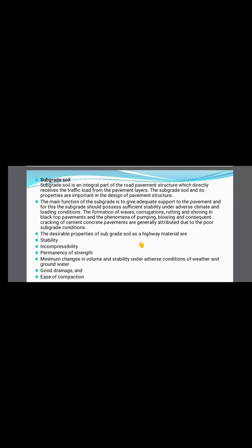So our subgrade should be such that whatever load you apply, it should not get compressed. That is incompressibility. And permanency of strength means the strength that we design at the beginning stage should be there throughout the life of the road. So that is permanency.